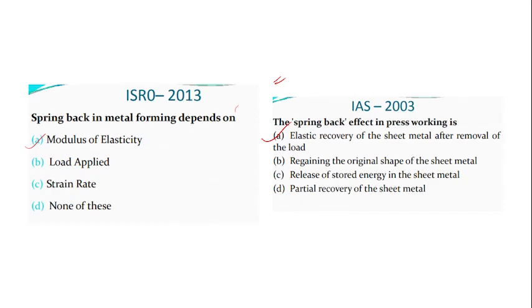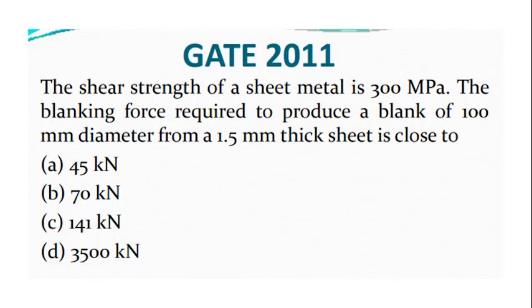See, it is not mentioned what kind of energy. Full area under the curve we considered as strain energy, right? So it is not mentioned. So we are not going to recover energy which is being stored after the plastic deformation, right? Okay, so it is not specific. That is why we are not going. If it is mentioned elastic, then we can consider this also strain energy or something. Okay. Now solve this question.